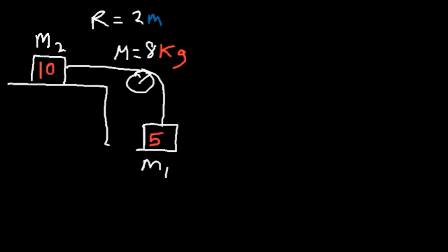So now let's use the second method. Let's use tension to calculate the acceleration. So there is an upward tension force, which we'll call T1, that slows the descent of the 5 kilogram block. Otherwise, without that tension force, the 5 kilogram block will descend at a rate of 9.8 meters per second squared. So it's decelerating at 2.579. So T1 is the tension force that slows it down.